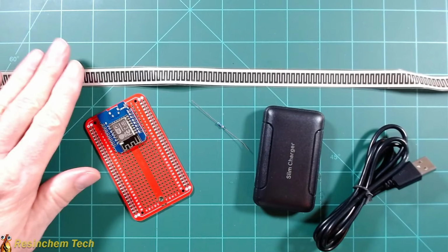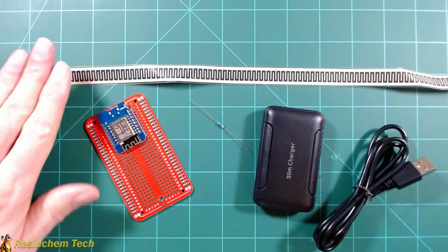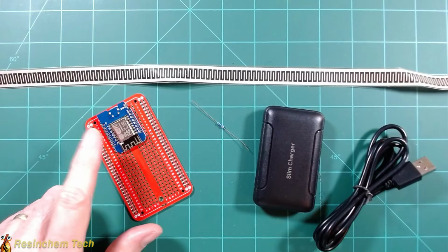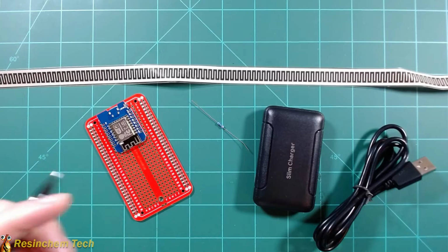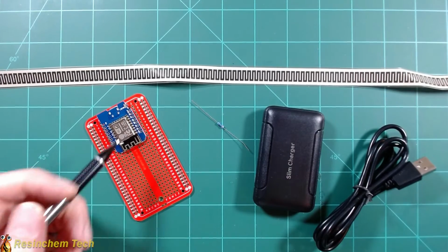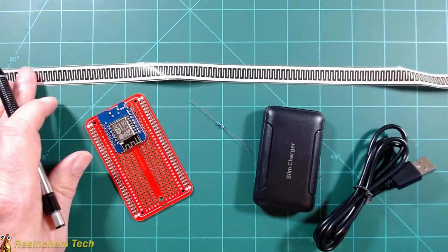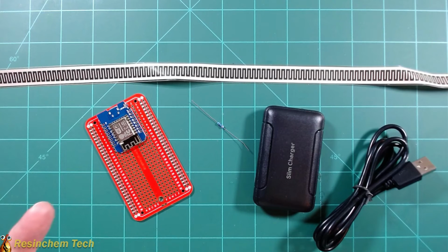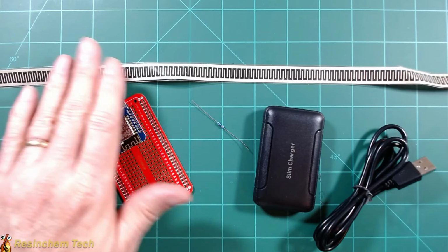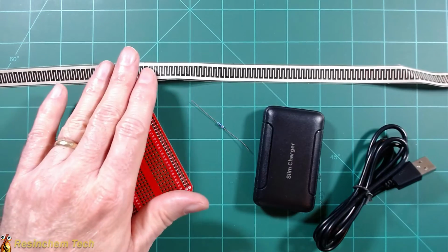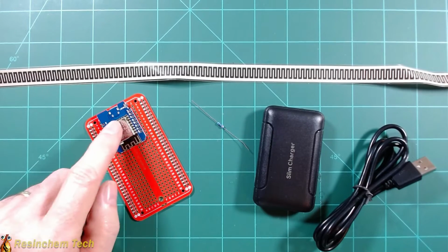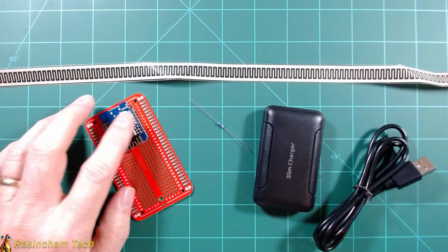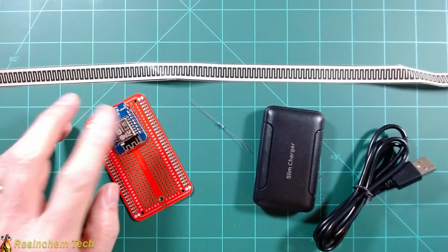Of course, we've got our force-sensitive resistor strip here, and after a little bit of testing, I decided I'm going to go with the Wemos D1 Mini, the ESP8266. I only need one analog input pin. Now, this strip is only about 24 inches long, so if you wanted a sensor for each side of a larger bed, like a queen size or larger, you would probably need two of these strips, one on each side, in which case you might want to go with the ESP32 because it has more than one analog input. But since I'm only going to need one for mine, I'm going to go with the D1 Mini.